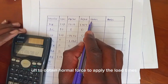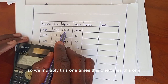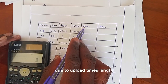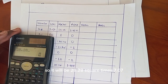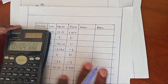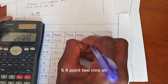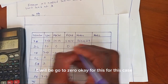To obtain the product of normal force due to applied load times normal force due to applied load times length, we multiply this one times this one times this one. So it will be 28.28 square times 7.07. It will be equal to 5654.29. This 0 times 10 will be equal to 0.